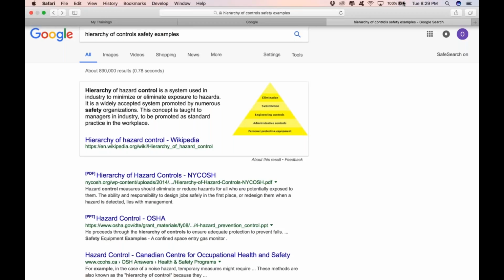Okay. And then, of course, let's talk about respirators for a little bit, right? So professional consultations would most likely be needed in providing adequate respiratory protection. A lot of times, employers will work with an occupational medicine doctor or some type of respiratory specialist, right? And make sure that respiratory protection is necessary for toxic atmospheres of dust, mist, gases, vapors, any type of oxygen deficient atmospheres. And remember that there's four basic categories of respirators, okay? So let's talk about what the four basic categories are.